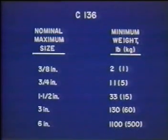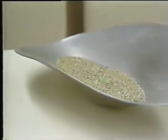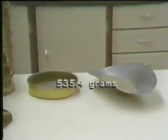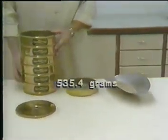The weight of the test sample of coarse aggregate or mixtures of fine and coarse aggregate should conform to this table of values. Weights may be from 2 to 1,100 pounds as nominal maximum aggregate size increases from 3/8 to 6 inches. The dry weight of the fine aggregate sample used in this demonstration is 535.4 grams.